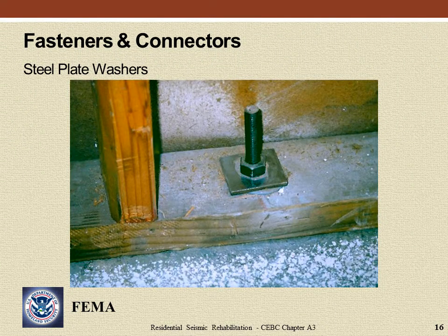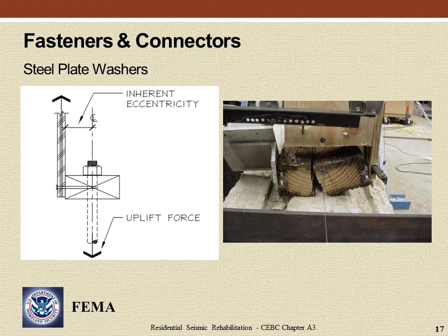Square steel plate washers are required on all new anchor bolts and recommended on existing bolts where it is possible to install them. Foundation sill plates split when shear walls are loaded in plane, resulting in the sheathing being pulled up at one end of the wall. Where sheathing is pulled up, the uplift is resisted by the anchor bolts, but this causes bending of the sill plate in its weak direction, allowing splitting at very low load levels, as seen in the right photo. Steel plate washers help to limit or delay splitting of foundation sill plates.